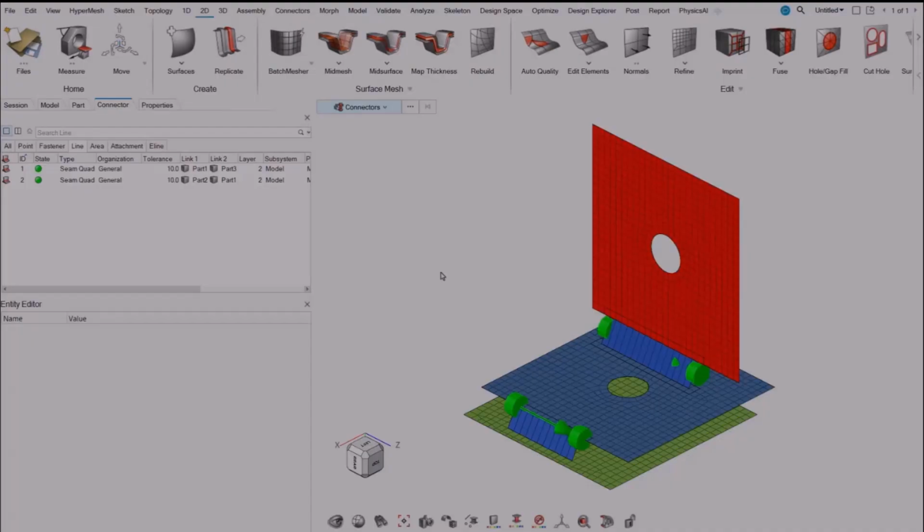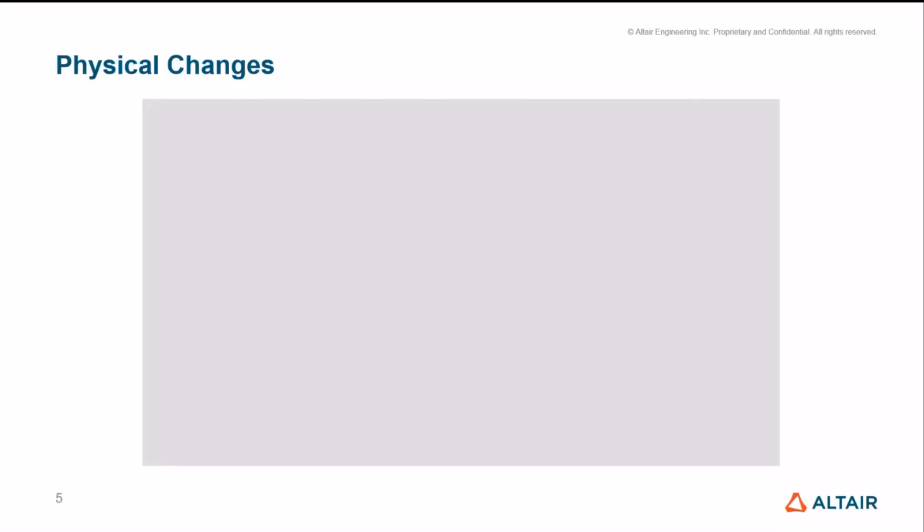A question I got was whether we need to lock in the movement of the link, or if it will also work when moving around interactively. So the answer to that is that we have to lock in the movement. So we have to enter the movement or click on the graphics area in order for the whole operation to be done. It will not be done interactively while moving around.